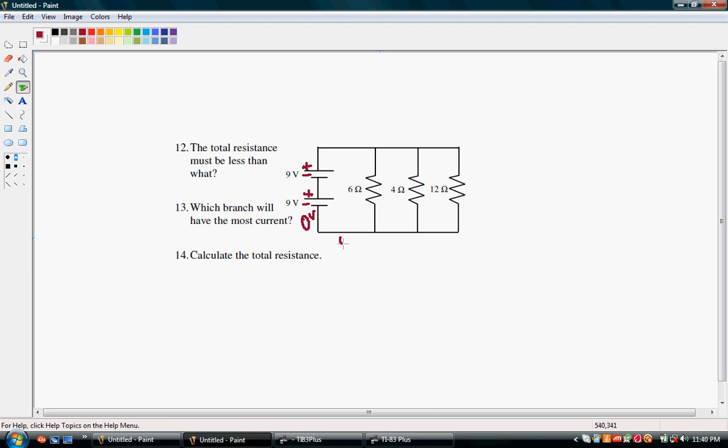So we can go ahead and map this out and go backwards. We know until we hit something we're going to have 0 volts. So we have 0 volts all along here until we run into these different resistors. Alright, and then we have 0 volts, but we go through a 9-volt battery. So we have 9 volts here, and we go through another 9-volt battery. So we have 18 volts here. And we will continue to have 18 volts all the way across until we hit something.